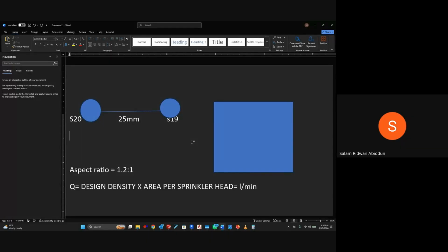But if I want to assist you, there are different types of sizes of sprinkler. We have the bulb, that bulb that ruptures. So we have 5 mm bulb, we have 3 mm bulb. Orifice too, it differs. Well, the area that it covers does not differ per se. What makes it different is your pressure. Do you understand? Your residual pressure.